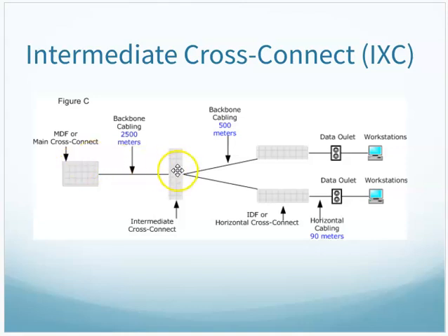I run a fiber link over to a building there, and then I split it out to maybe the 2 or 3 neighboring buildings around it using shorter distance fiber optic cable into those buildings. So it's kind of a special case, but it is that branching out point, that intermediate cross connect. I like to think of it as going across a college campus with a fiber, then branching it out to 2 or 3 buildings that are near that.